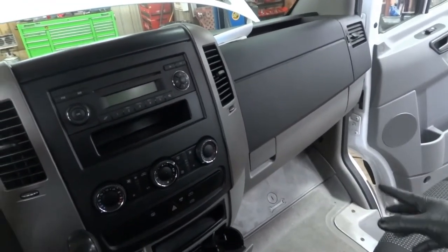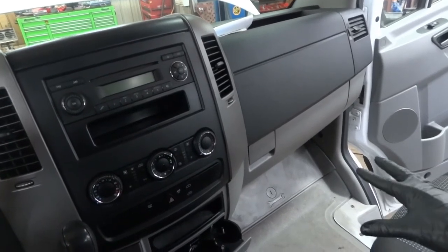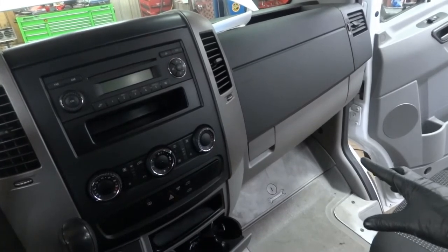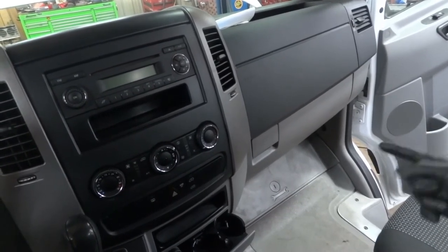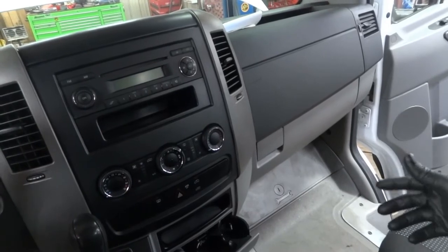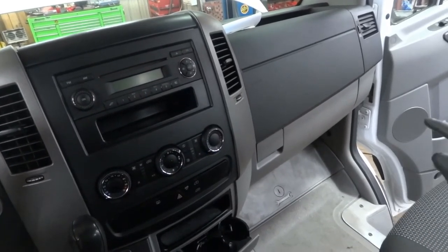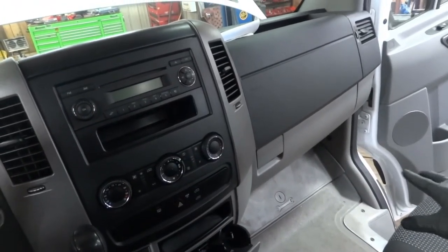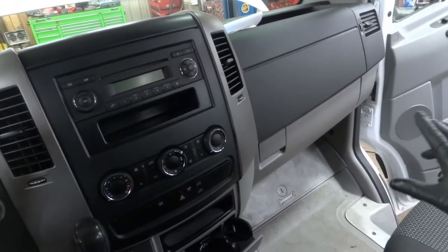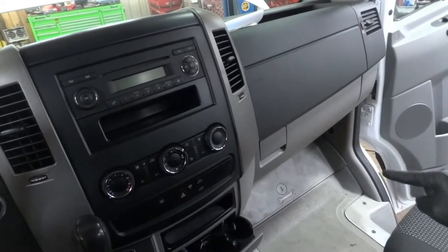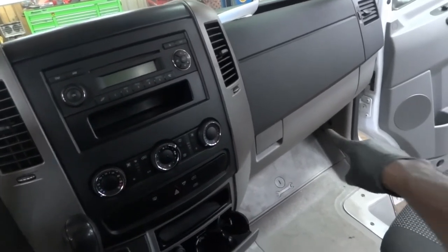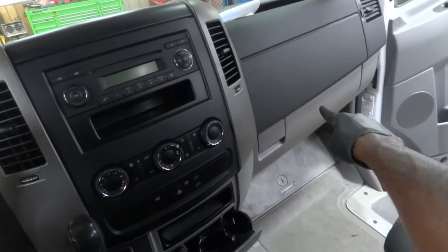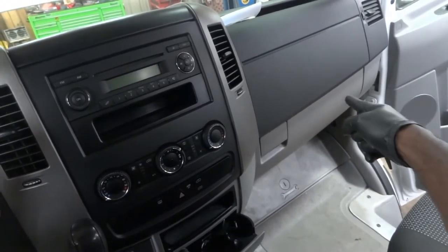Okay, so let's stay low-key here. Let's not bring out all the big guns first. I am going to just go to the blower motor itself and do some checks there. We can use a test light to see if we're getting any power and ground at the blower motor. So the first thing we're gonna do, just based on the location and how easy it is to get to the blower motor, that's why I'm going this route. I'm going to remove the glove box, which only has a couple of screws. So let's remove the glove box and get access to the blower motor.